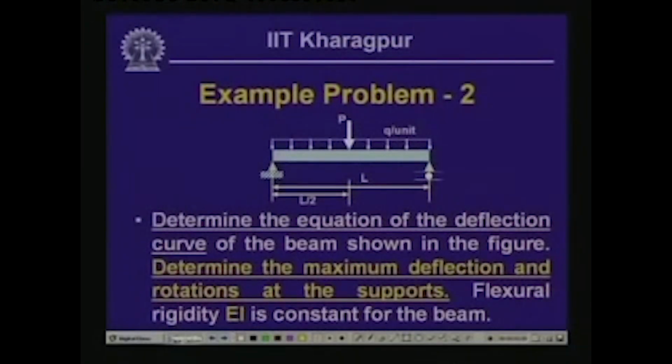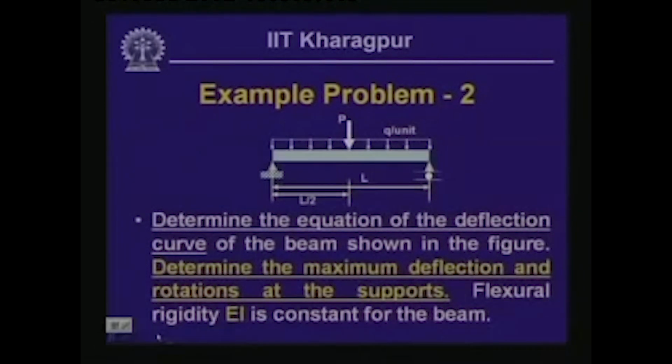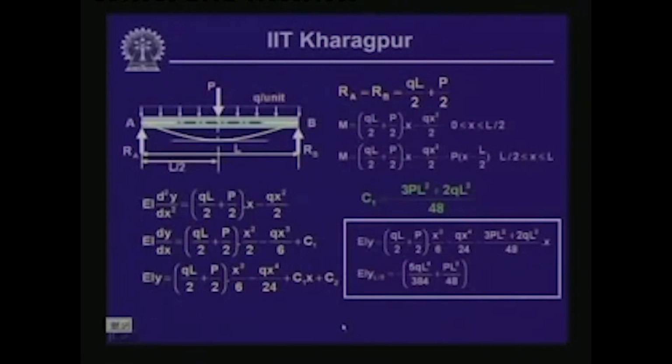The reason behind this is that the deflection which we are computing is a linear function of the load which we are applying, and hence this superposition is valid, and you can get the deflection by using this superposition technique. Now, let us look into this particular problem, that first we compute it the way we are computing now, and subsequently if we impose the method of superposition, then what happens.